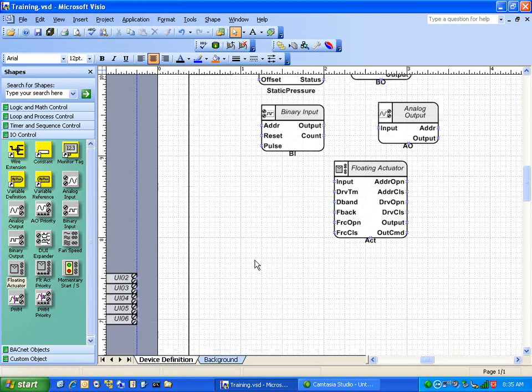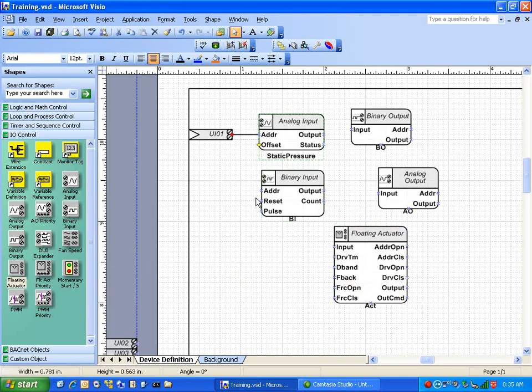The other thing that's not on here, if you happen to be doing a VAV controller, the actuator object and the transducer object also have COVs put in there for when you're reading your CFMs. A lot of times those are a big one too, because the CFMs on a VAV controller can be pretty bouncy. Depending on it, I'll usually put in a minimum of 5 CFM for a COV on a VAV box.